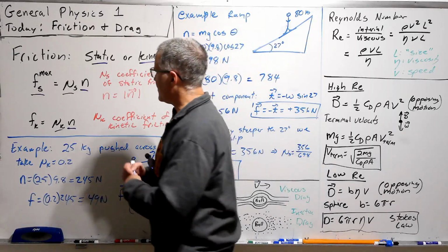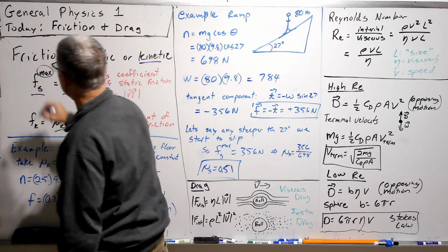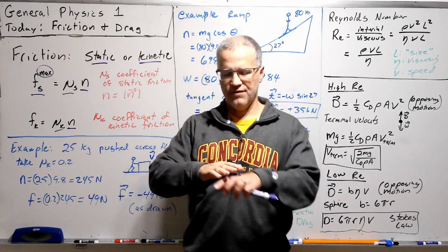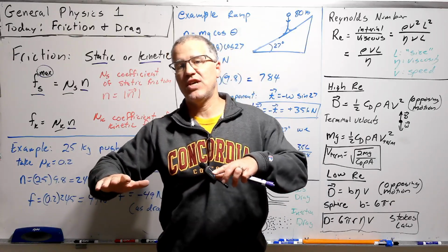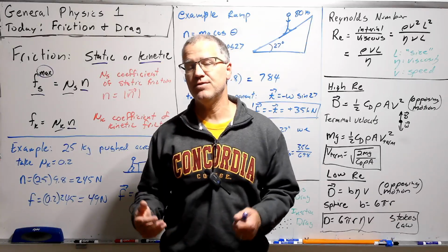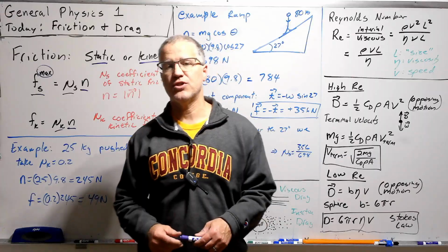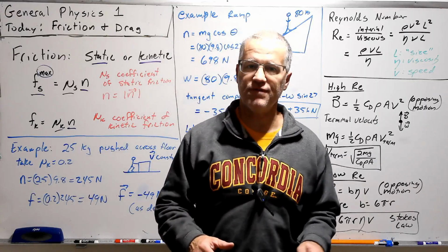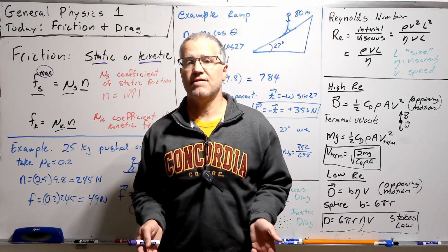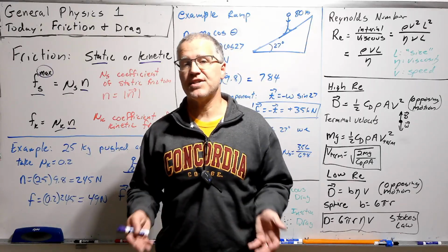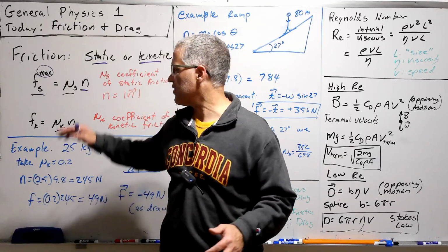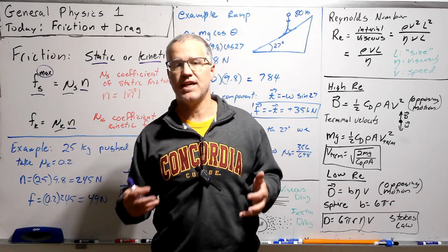Now notice here we have a max here. This is telling us what's the maximum frictional force before slippage happens. So I'm standing here with my shoes. There's good friction, good coefficient of friction between my shoes and my wooden floor here, but I'm not really applying any of that. That never has to come into bear because I'm not moving anywhere. I'm not trying to move anywhere. So static friction, you're not moving, but I'm not opposing any kind of motion.